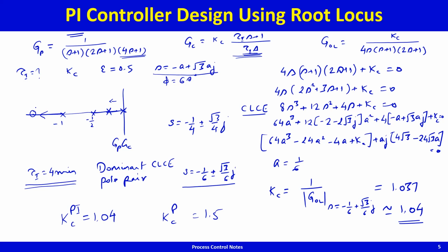And now you can see the root locus would be of this kind. My breakpoint has moved between -1/4 and 0.